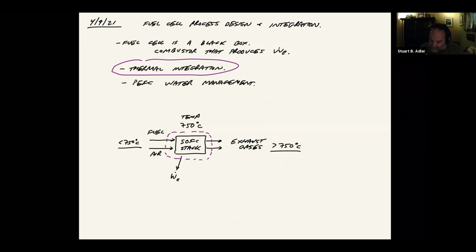So this gets to one of the essential dilemmas that you have with a SOFC. You think about our requirements. We have to keep the system hot because the thing has to operate at high temperature. But as I showed you last time, we have to get rid of the thermal energy. So we have to keep it hot, but we have to cool it. Sounds like an oxymoron. As chemies, I think we're used to that idea, right? Because keeping something hot, that has to do with temperature. Cooling something has to do with thermal energy and enthalpy. That's the essential issue. How do we arrange the situation where we have cooler gases going in, hotter gases going out, removing that thermal energy, but keep the temperature at 750.